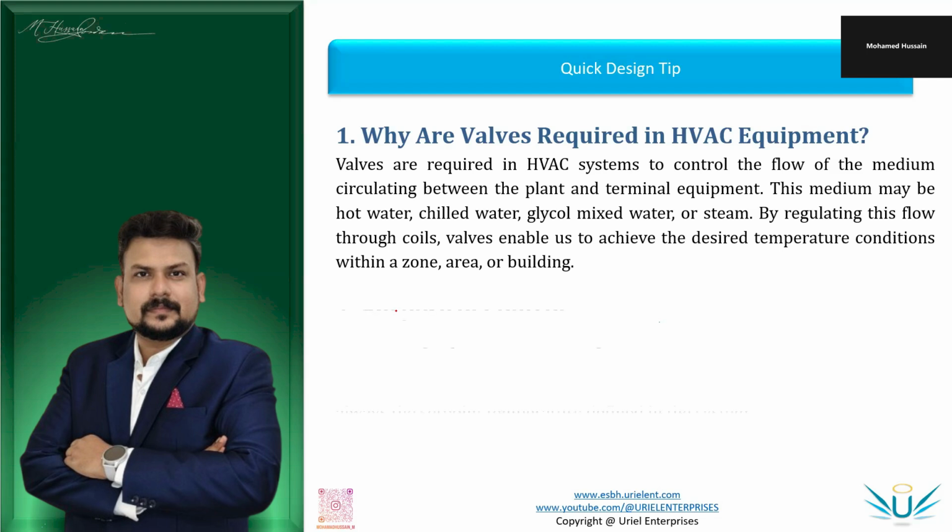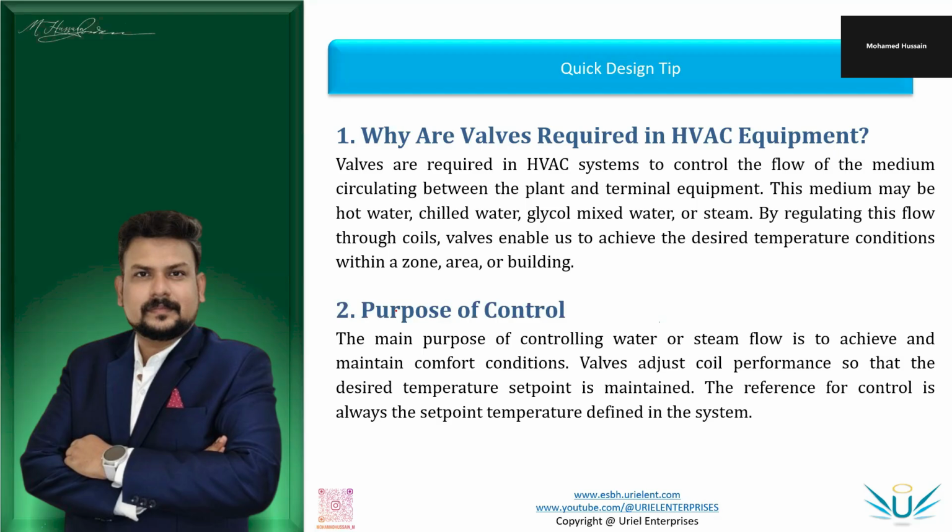The control valves are controlled by giving a reference temperature set point, which is processed in the PID loop. Those are programming elements, and we don't need to go into a deep dive. Just understand that the temperature-based control signal is given to that particular valve, and accordingly it is going to control the entire flow. So now we'll look at that.